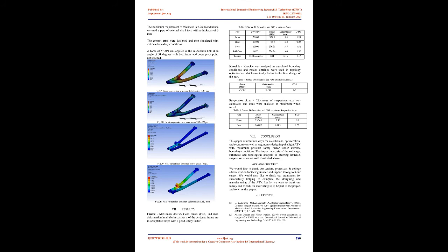The results of the analysis. D. Topology optimization. Topology optimization ensures that the designed part doesn't weigh more than required without any compromise in the factor of safety. Any extra material adds to the cost of manufacturing as well as unsprung mass, and due to the extra material, loads on moving parts are higher than necessary, and hence energy efficiency is also compromised. We can see that there are some areas where the amount of material is more than necessary and there is scope of material reduction in those areas.